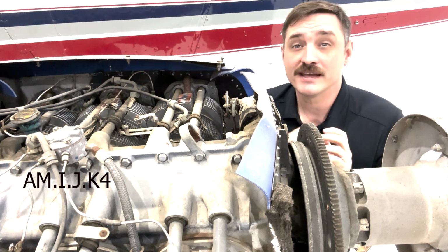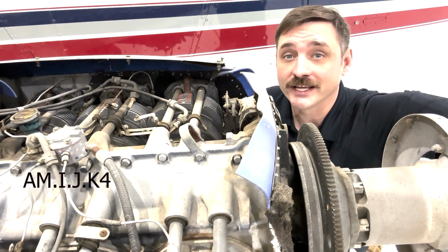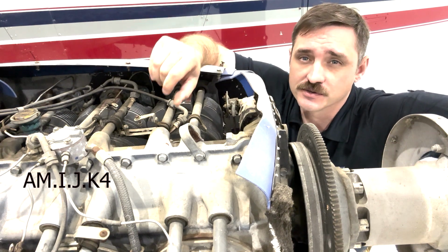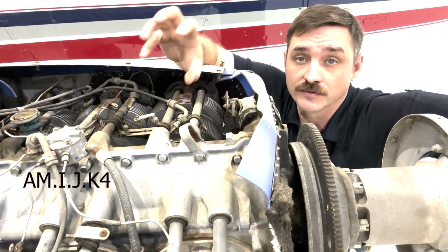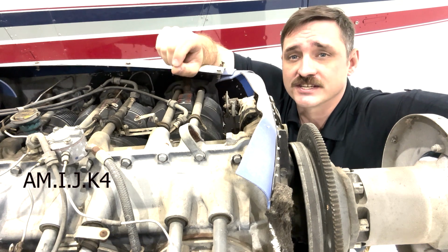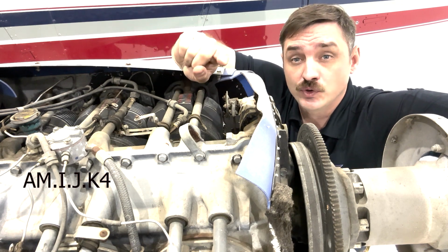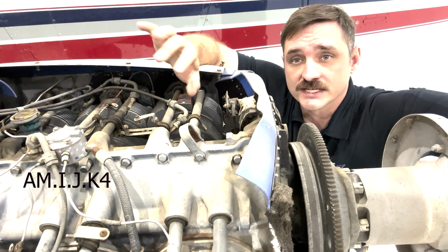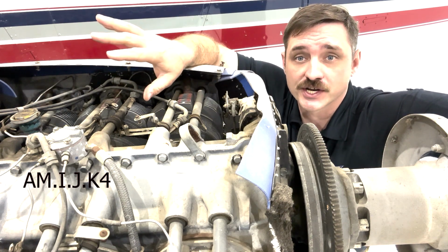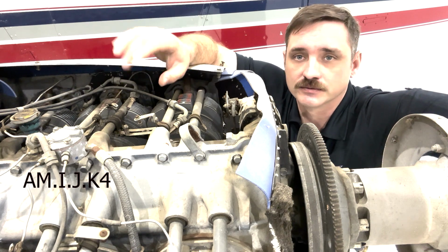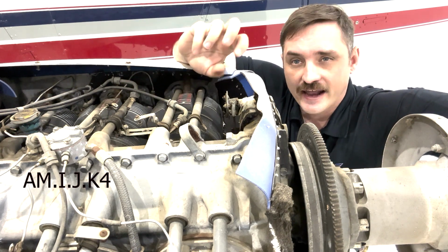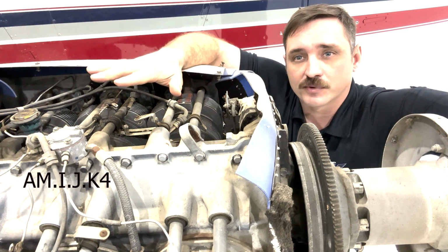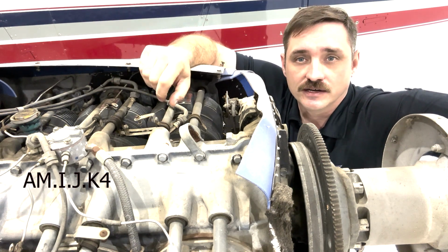Now, it may seem to be a little nerdy to really dig into the heating effects and the math that goes into the fuel cooling. But there's actually several engines that use fuel to cool the engine, because as the cool fuel runs over the top of the engine on its way to the combustion chamber of reciprocating or a turbine, either one, it actually grabs heat and pulls it away from the case, lowering the operating temperature of the engine.